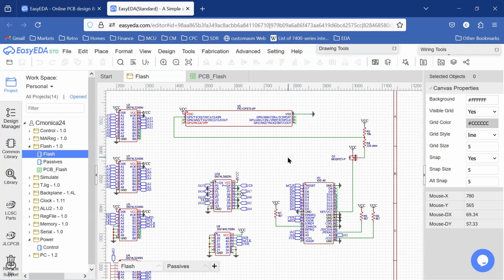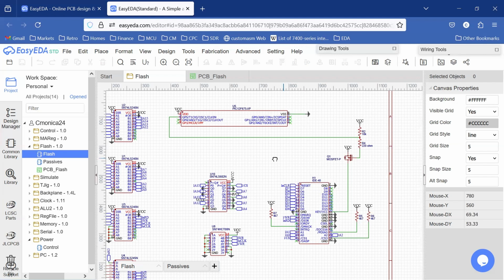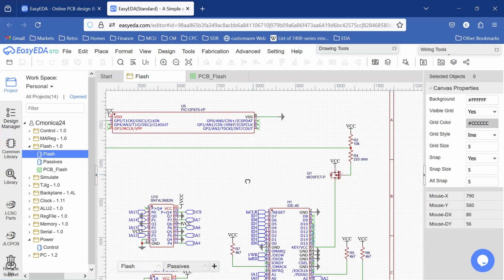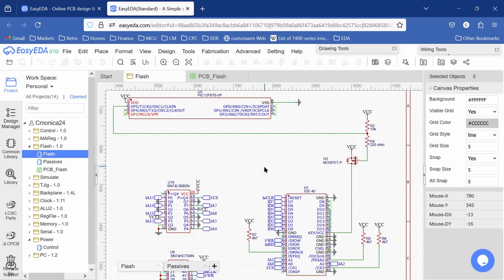Now, I mentioned that our soft start power supply was going to give us potentially a problem with our compact flash card, because the compact flash card can run in 3.3 and 5 volt operating levels, and it makes the determination which level to use based on the power that's applied to the compact flash card at the time of power on.